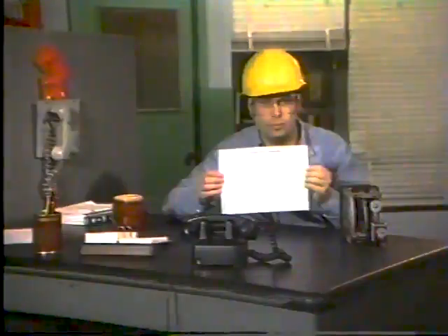There's one other document that you'll probably use when you tune a controller. It's an instrument calibration record, or instrument history record as it's sometimes called. The calibration record identifies calibration settings for specific instruments. For example, here are the calibration settings for the cooling water temperature controller. And this is the general information that was entered by the last technician to calibrate the controller. This general information tells you how the technician calibrated the controller.